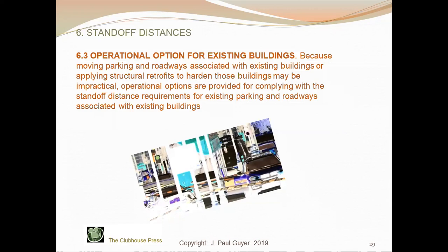The access control in those situations must be established at distances in accordance with tables B1 and B2. The assumption is that by establishing access control into parking areas, there will be lesser opportunities to enter the parking areas with explosives in vehicles.